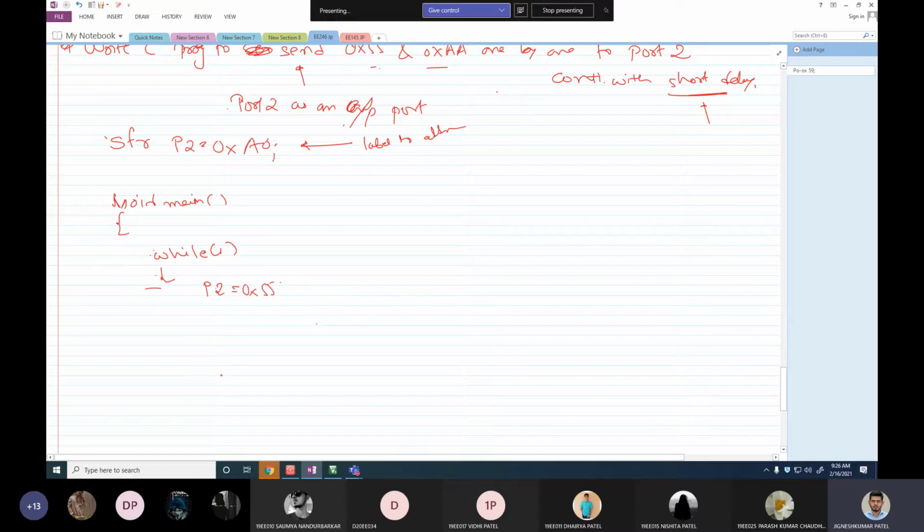So I should write a delay loop. How to write a delay? We know that we are going to use a for loop, whether it's a short delay or a long delay. I know I should stick with 250, so I'll write i less than 250, i plus plus. Whenever you are forming a delay, this is the only thing you are going to write: a for loop followed by a blank body. So this is my short delay.